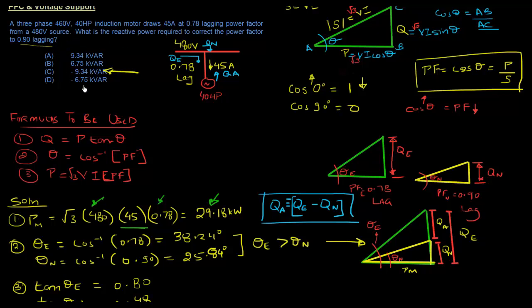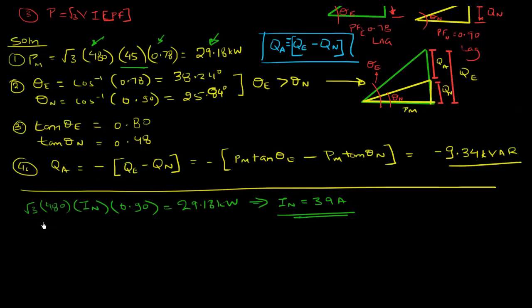And the calculations we did today is what you'll do to find out how many kVARs you need to introduce. Once you have your kVARs, then you can find out how to size your capacitors that you'll introduce in the circuits to bring those kVARs to the system. So that's the problem today that we solved.